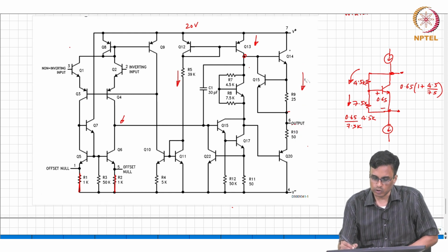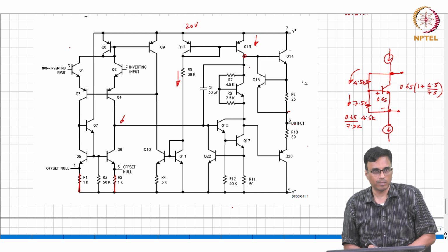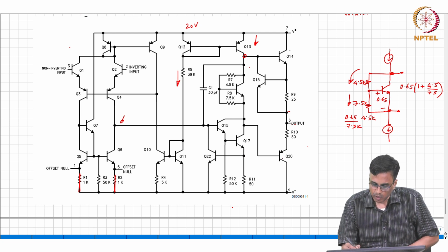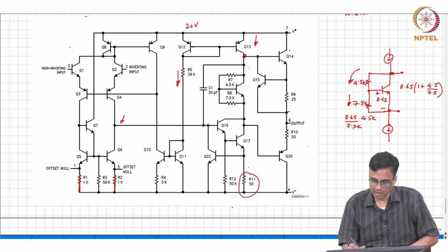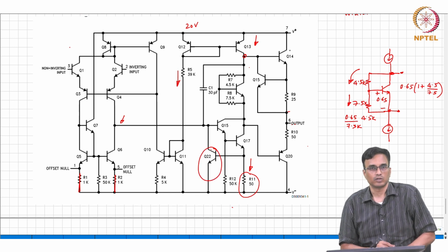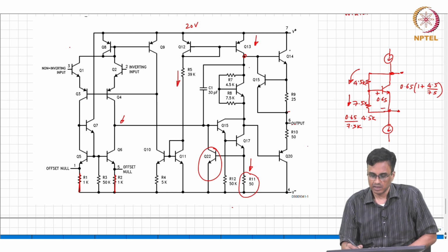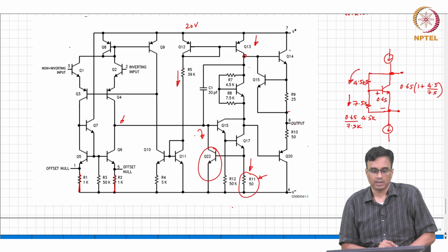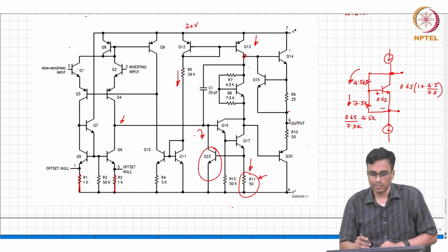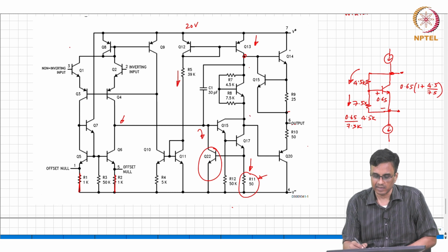So, there is some resistance to limit the current to some degree, and you can as well sense if there is a lot of current going to flow through the PMOS transistor, which basically means that there will be a lot of current flowing here. So, again Q22 is going to turn on the moment this voltage drop becomes very large and pull all that current down. So, for all practical purposes, tri-stating this whole thing, right.